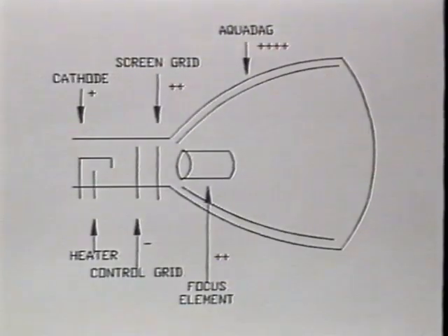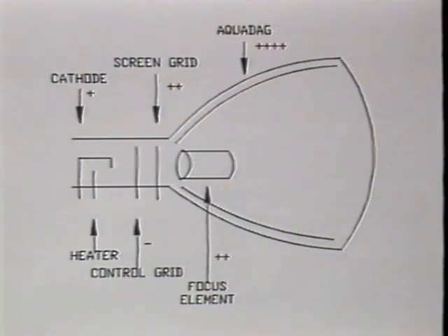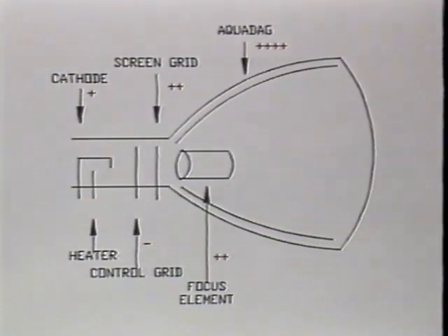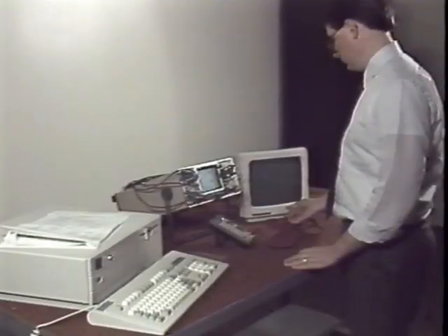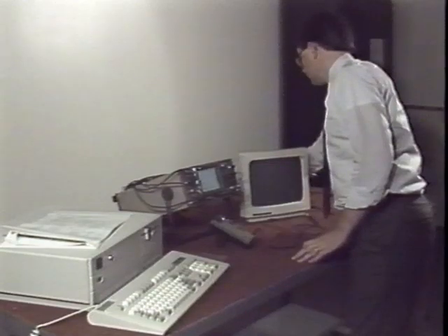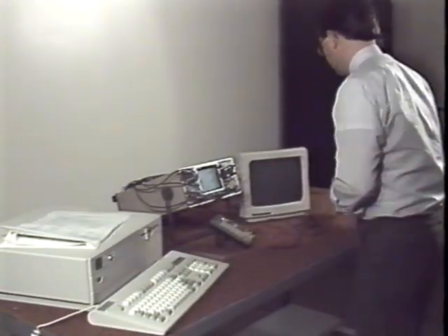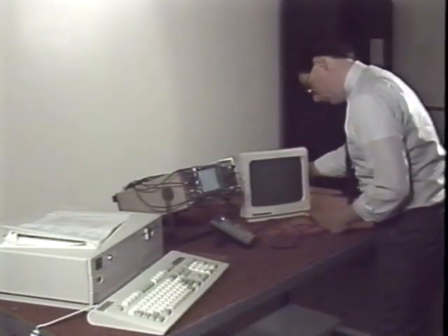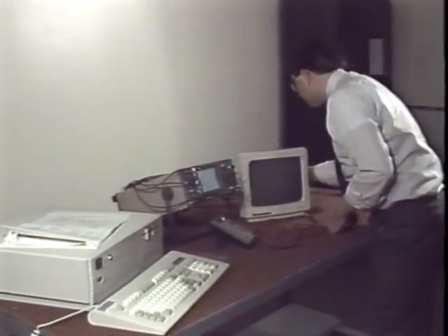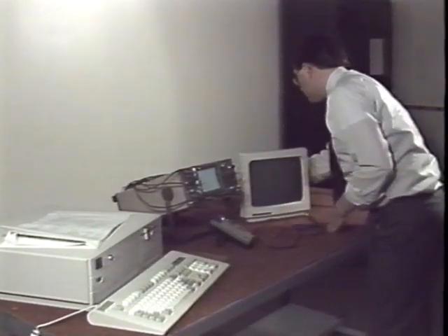Now that we have a stable display, we can move on to the tube bias adjustments. The first of these is the internal or sub-brightness control. This adjustment varies widely from one monitor type to another. In this unit, it is done in two parts. First, we set the external brightness control to its maximum level and then remove video input. Next, we adjust one of the sub-brightness potentiometers until the raster is just visible. This is the maximum brightness level that the user will be able to select.